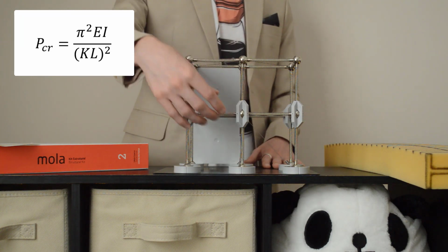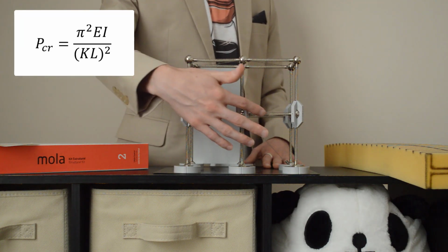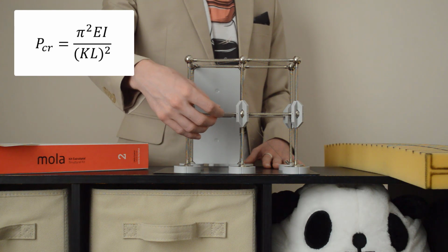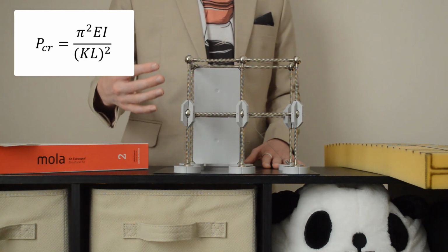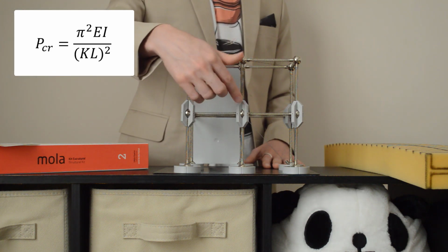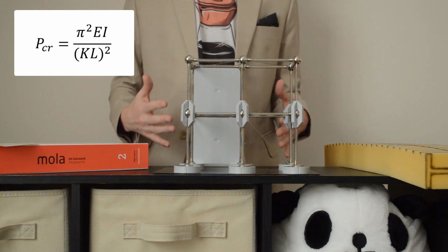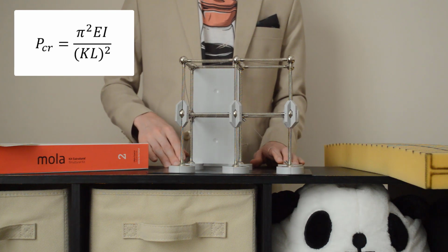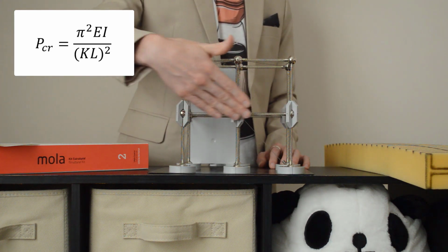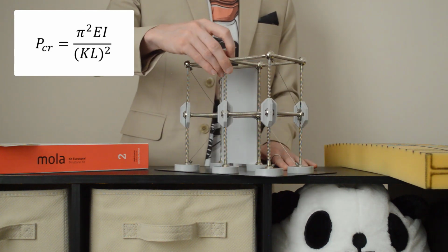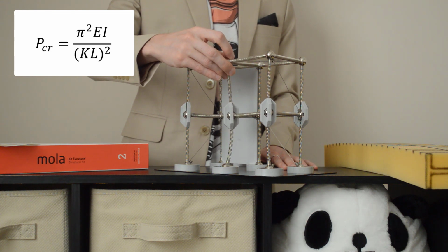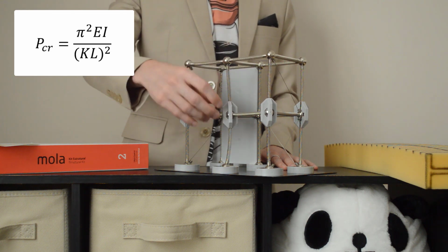So in other words, when we provide these two beams for this column, what we've done is we've improved the buckling capacity for this column in this direction. However, as I said, column analysis is a 2-dimensional game. So if you improve its capacity in one direction, you really haven't affected the overall capacity of that column at all.